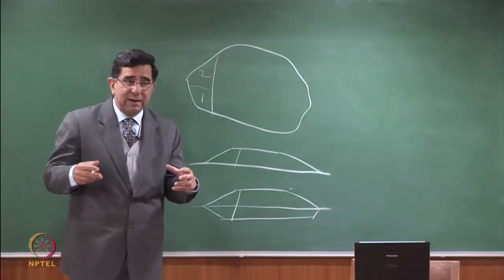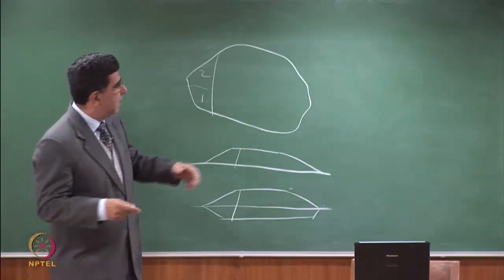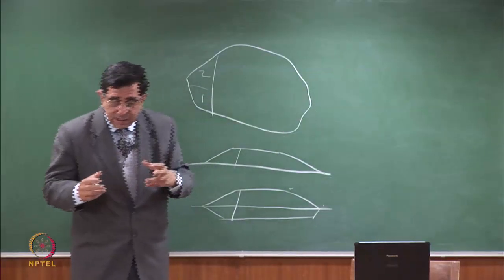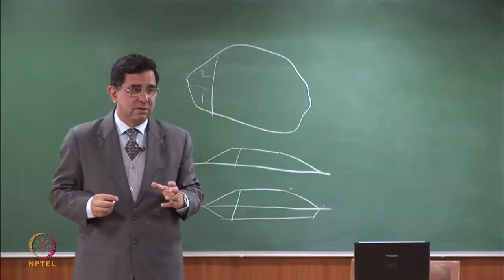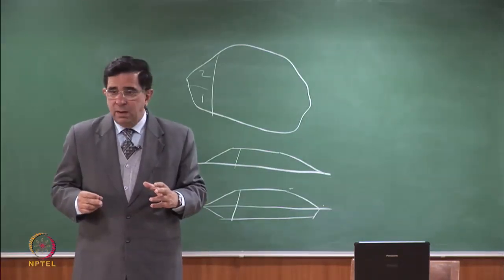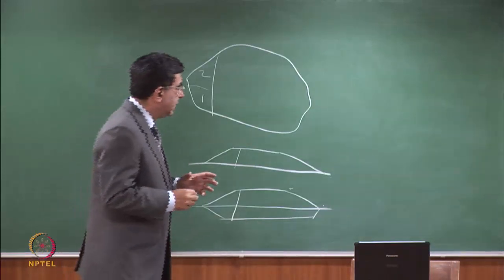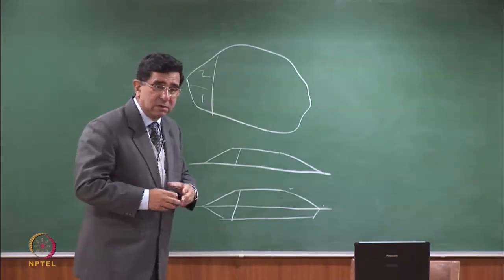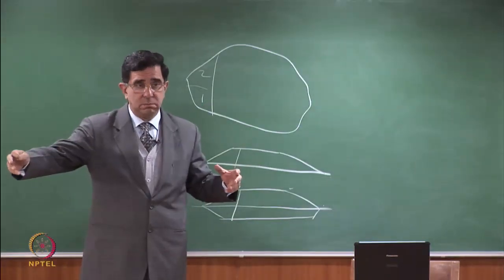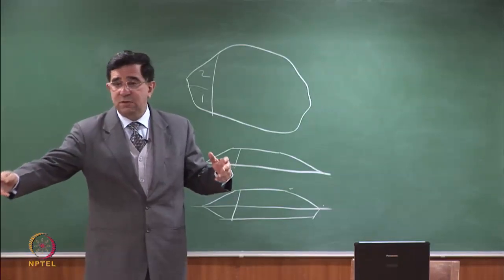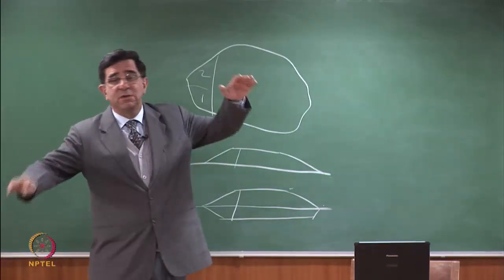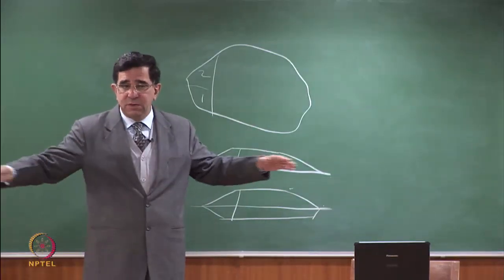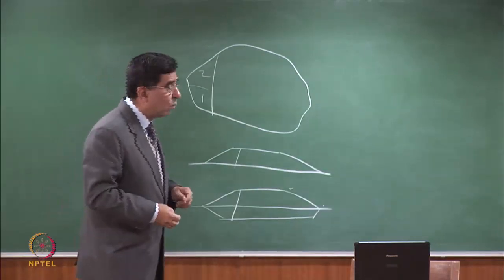And if I have to start collecting the leachate from the first phase, suppose I make a well here, then this leachate has to travel all the way across. So typically, you will have a leachate well for one annual phase. And I have said this earlier, that if you think that you can take leachate from one end to the other, suppose this is a 400 meters long path and you have a 2% slope, then you have an 8 meters elevation difference between the two sides. So normally it is not done like that. You have an accordion arrangement and each phase may have its own low-lying area.